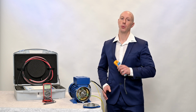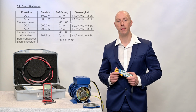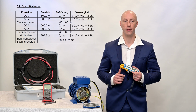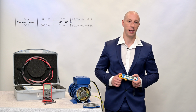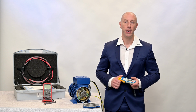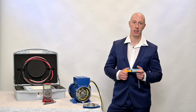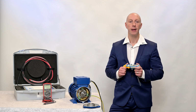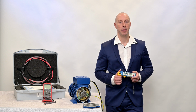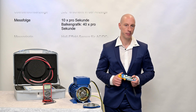However, there are two major problems with this measuring method. Firstly, the current clamp cannot detect high-frequency currents generated by the frequency inverter, which means that the measurement result only corresponds to a small part of the truth. The bearing currents that are to be measured flow in the high-frequency range, so at several kilohertz and megahertz. Secondly, only one value can be read on the current clamp, which is also subject to a certain inertia.